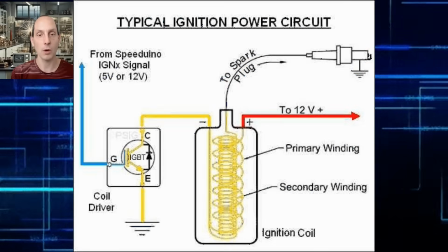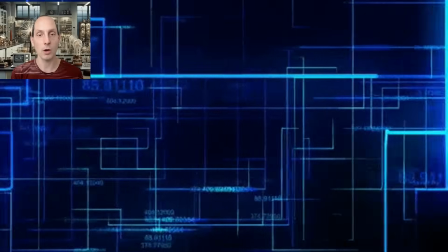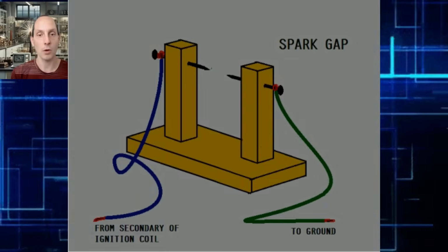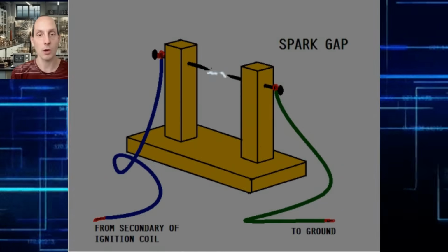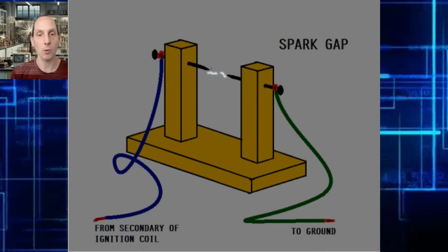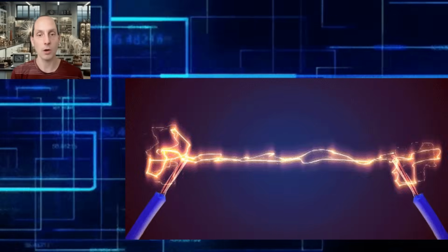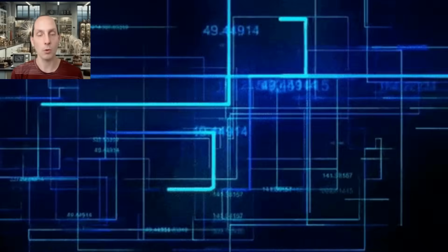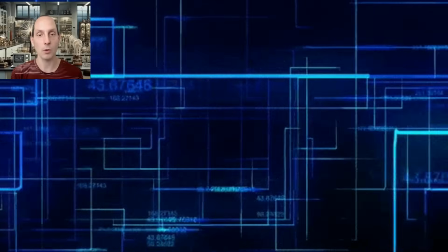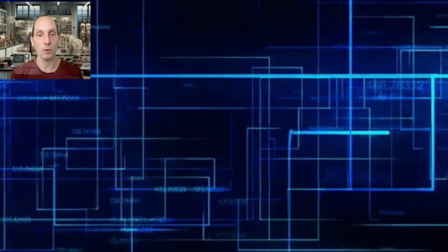However, engineering and maintaining the dynamic regime of a spark gap is non-trivial. The spark gap's performance depends on its operational zone, e.g., region A versus region B in Paschen-like curves, gas composition, electrode spacing, and field pre-bias conditions. These systems are nonlinear, stochastic, and sensitive to environmental conditions, making them difficult to stabilize or reproduce with precision.